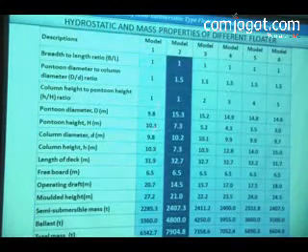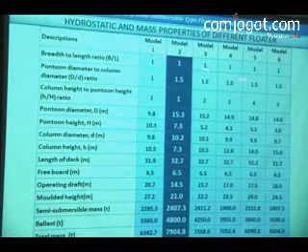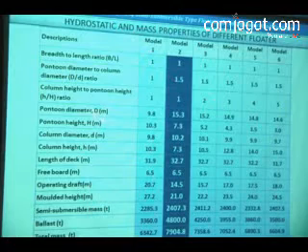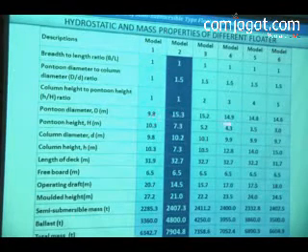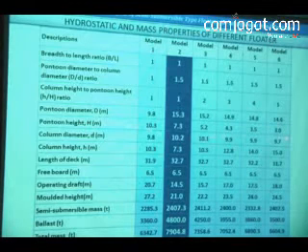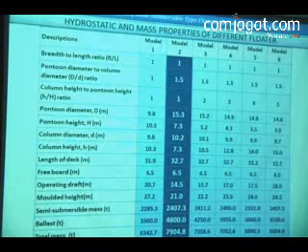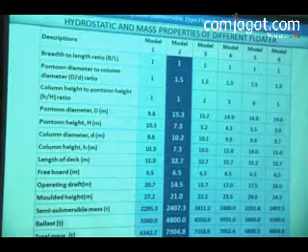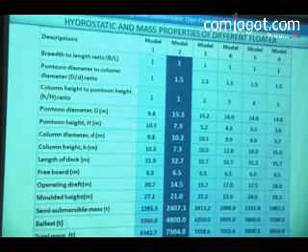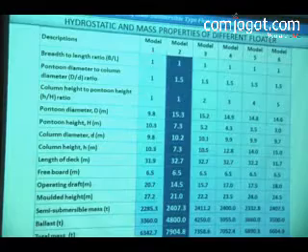These are the different hydrostatic and mass properties for the 6 different models. The pontoon diameters vary from 9.8 meters to 14.6, along with the pontoon heights, the column diameters and the column heights. Let me skip all this data. It's important to know that all these semi-submersibles have a fixed metacentric height of 1 meter.